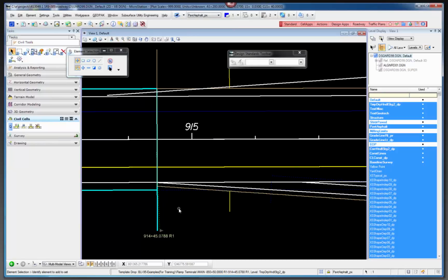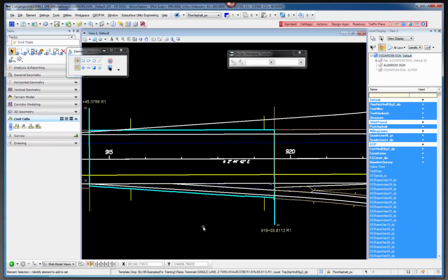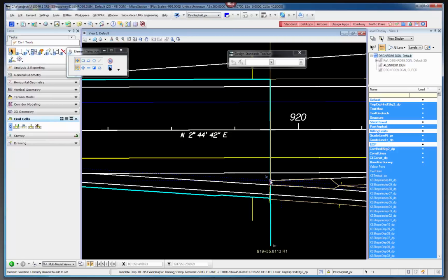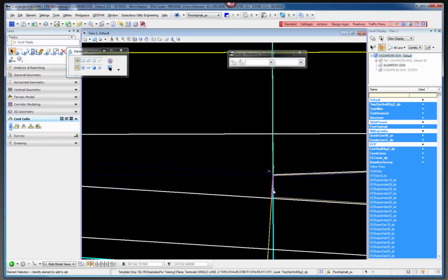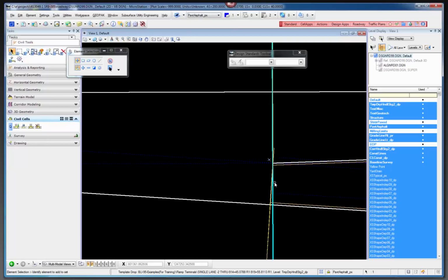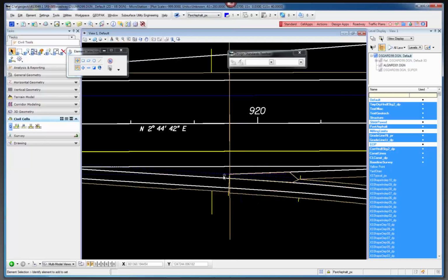Now in this case, the next template drop, I'm just highlighting it here, is the area that goes right when the ramp physically starts. It is not a full ramp until it gets out to the 12 feet section, and that's according to the standards. Then it goes to where the end of the physical pavement is, not where the shoulders are, but where the physical pavement is. In this case, I believe it's defined in the standards as 19 feet, and that's where I'll stop that template drop.